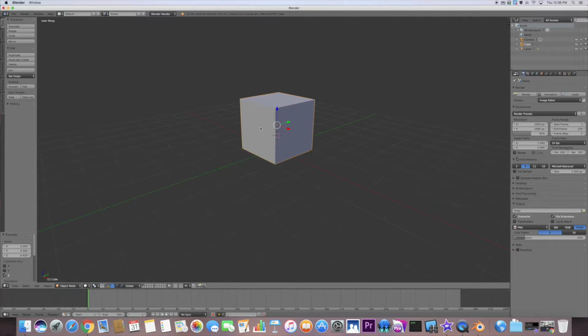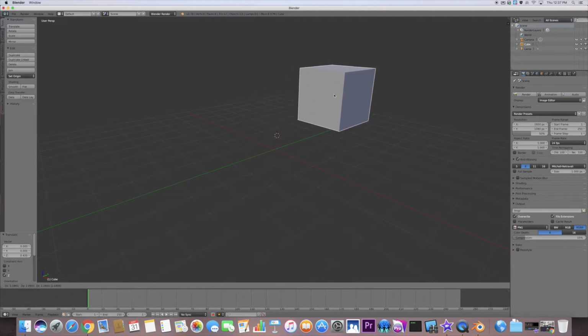Once we start building shapes and once we start making complex objects, a lot of times we don't want the objects to be moving across all three axes. Let me give you an example. Let's say I wanted to take this block and move it back further on this axis, but I didn't use the Y axis lock. So I'm going to press G and try to put it over there as best as I can. Let's say like that. Now in this view, that looks like it moved over on the Y axis nicely.